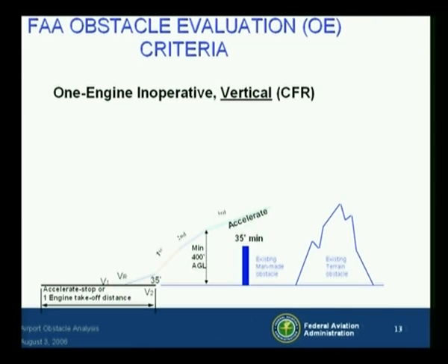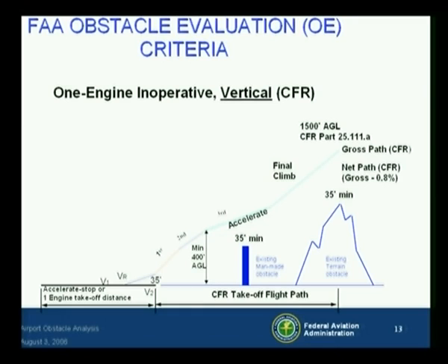As you get into the third segment climb, which is after 400 feet, 400 feet is the minimum altitude that the operator can start any configuration changes, such as retracting flaps or reducing airspeeds or anything else. But at any rate, after 400 feet, the operator has the capability of proceeding to the final 1,500 feet endpoint at V2 with takeoff thrust and takeoff flaps, which would be max performing the airplane the best it could possibly do. Or it has the capability, if it so desires, to level off at 400 feet, start the flap retraction